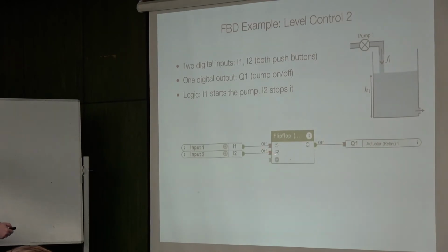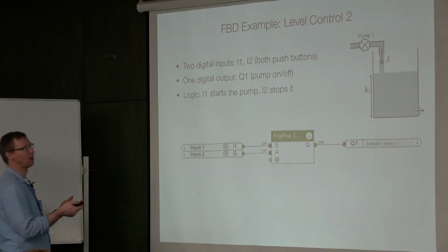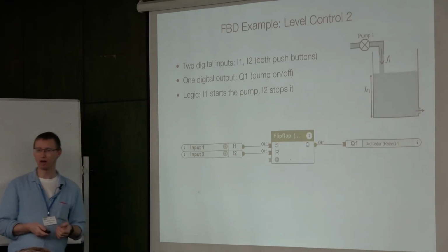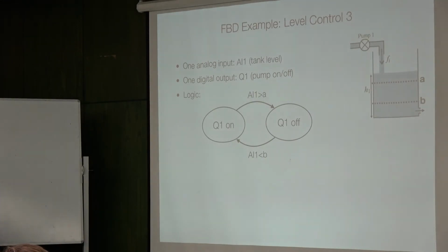That means that we take the set reset block from the library, and we connect the starting button to the set signal and the stopping button to the reset signal, and we connect the output directly here. The nice thing about this particular environment that we will use for exercises is we do not need to do memory allocation. Trust me, if we were to do that, we would be doing it for half of the exercises and nothing else. Okay? So here everything luckily is tackled by the platform itself. So this is still just running the pump or not running it. So let's get real control involved.